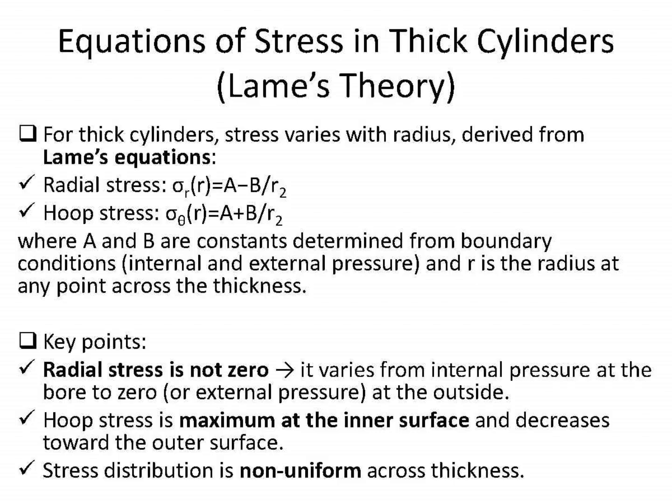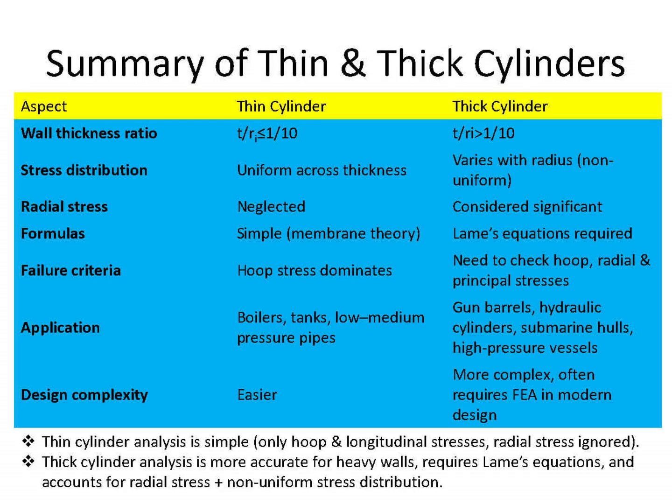Slide 12. Summary of thin and thick cylinders. Thin cylinders have uniform stress distribution and use simple formulas. Thick cylinders have non-uniform stress distribution and require Lame's equations. Thin cylinders are used for low to medium pressure applications, while thick cylinders are used in high pressure applications such as hydraulic cylinders and gun barrels.